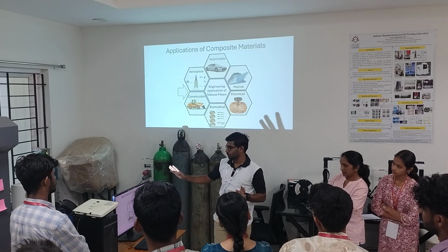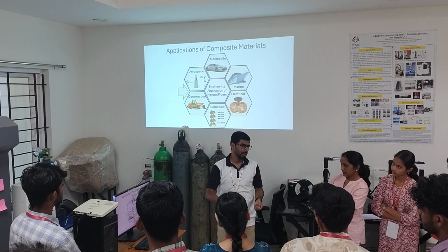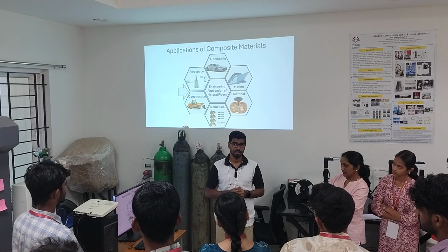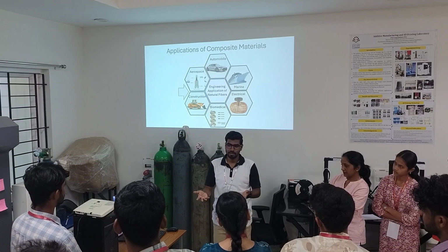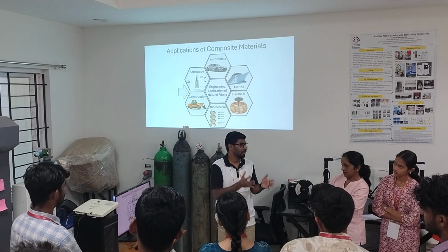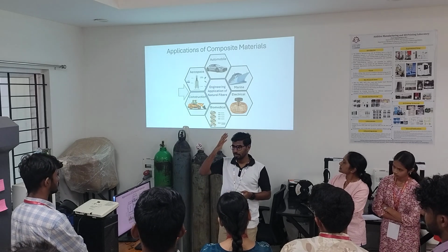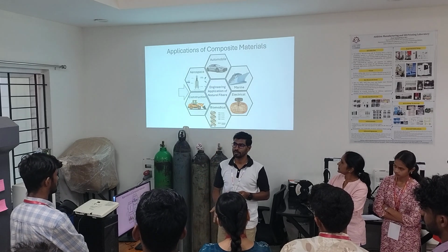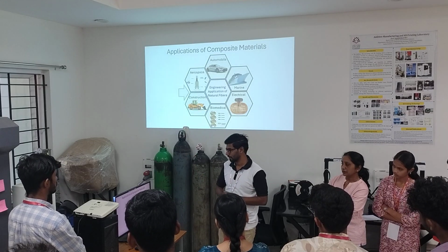Huge time goes into making those composite materials, and that is done with the help of the hand layup method. I should say it is twice as safe compared to using panels and riveting them together, because there were lakhs of rivets. If any one of those fails, we have the risk of failure of the whole launch itself.